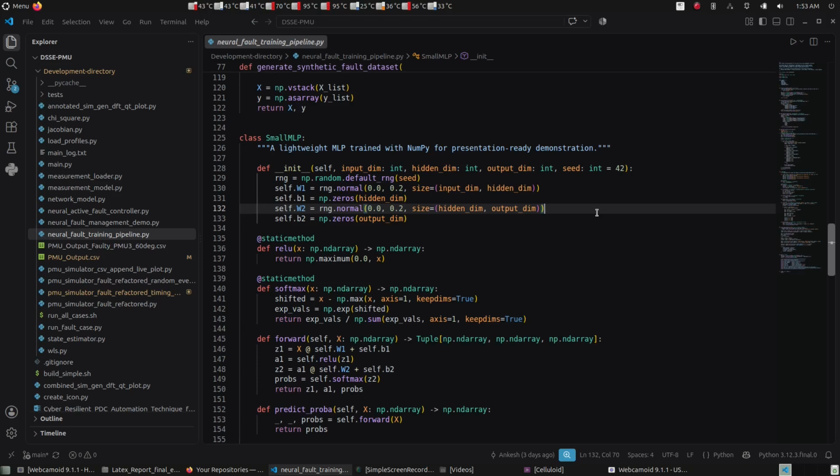So for example, a particular maxima happened at 9 amperes and with a certain degree of phase shift, say for example plus 10 degrees or plus 20 degrees, and this particular combination is more prevalent when a synchronization fault or a bad magnitude fault happens in my power line. So I'll assign a kind of probabilistic weight, that if this kind of combination happens, then there is a 90% or 95% chance that this is going to be a magnitude-based fault from the bad PMU. That way I develop a model which saves these occurrences, what we call outliers, in a separate vector, and then we use this information to accurately predict what's happening in my PMU in real time when it is running.